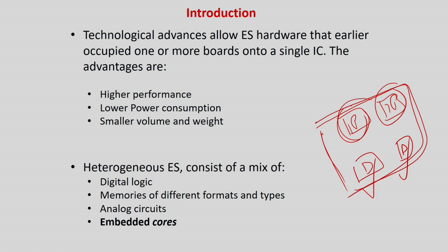So what these IP vendors will do is, along with the IP cores, they will also give you the test patterns which are required to be tested. And one more thing, sometimes they call it a wrapper. They give a wrapper, that means the way to access these IP blocks in test mode and normal mode, because that is the entire circuit given to you. You can read some other books also on test based hacking.